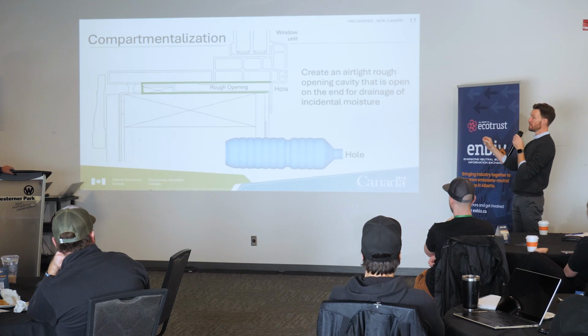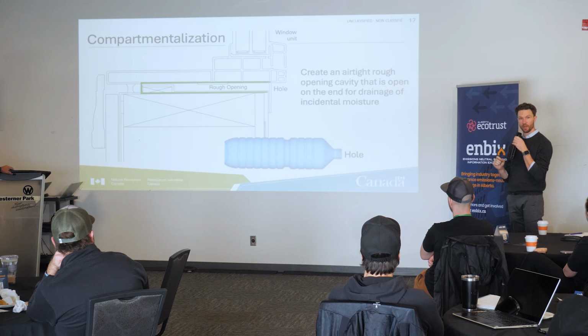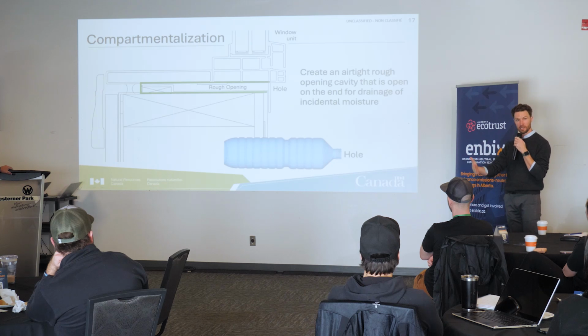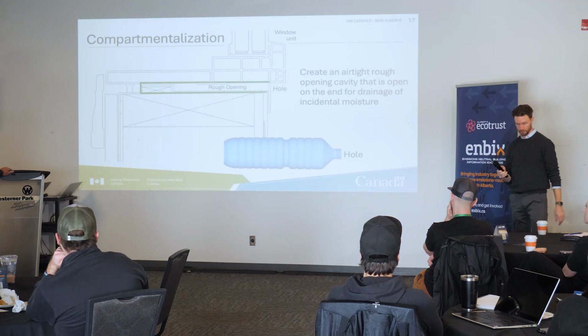So air tightness of the assembly and openings for drainage are different things. And I just have to highlight that, right? We understand now that houses don't need to breathe. Houses need to be as airtight as they possibly can to prevent moisture from getting into the assemblies that we're insulating. And then we have to control water by allowing proper drainage planes and openings from the exterior, keeping in mind where those planes of protection fall. Yeah, that's a really good way to illustrate it.